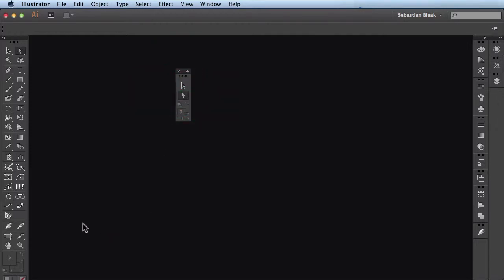One of the really cool things about it is that I'm able to add some of the Astute Graphics plugins. So you see over here in this section of the panel, I'll grab one of these tools. I'm going to hover over the Path Scribe tool, and I'll click and drag, and now I'm able to add it to this list here. Now there's some more tools that are sharing the same stack, and in order to get to those, I'm going to click and hold it down, hover over this edge, and then release.